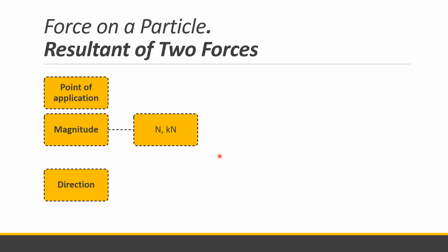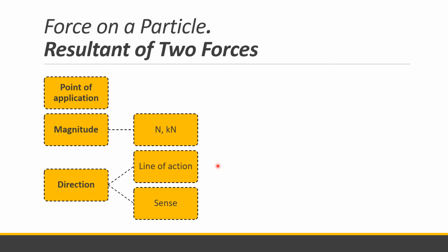And the direction of a force is defined by the line of action and its sense. So when you say line of action, it is an infinite straight line along which the force acts. So it is characterized also by an angle it forms with some fixed axis.